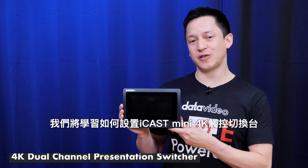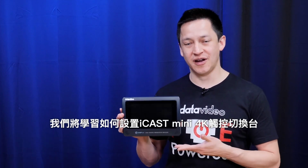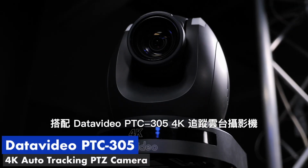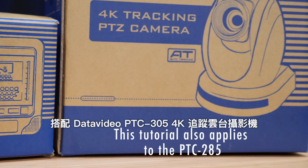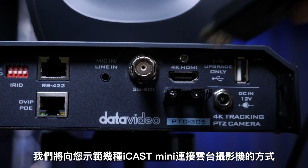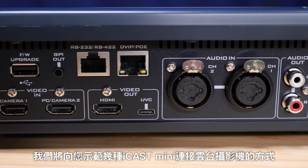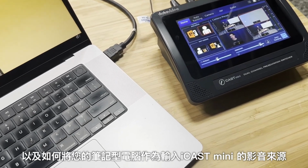In this video, we're going to learn how to set up the iCAST Mini 4K dual channel presentation switcher with the Datavideo PTC305 4K auto tracking PTZ camera right out of the box. We're going to show you the different options you have in connecting your PTZ camera to the iCAST Mini, and also how to set up your laptop as a video and audio source for the iCAST Mini.